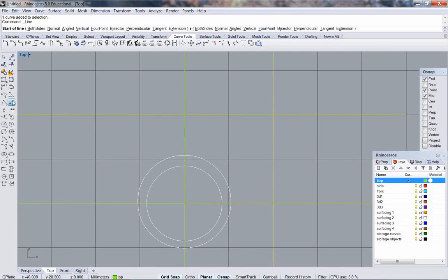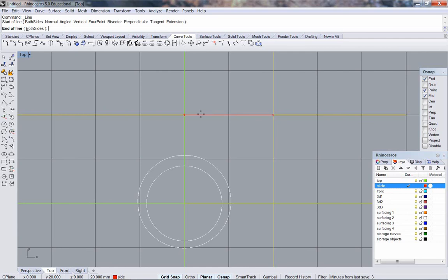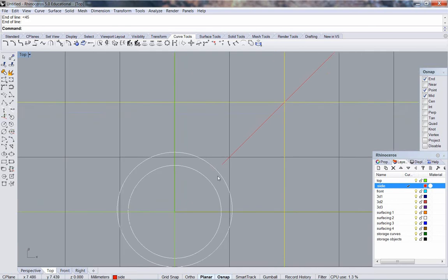And while I'm at it, draw our miter line. Starting here, constraining 3 things in this case. I want both sides, well actually 2 once again. Really the only thing I need to constrain is direction. So backward facing arrow, that's shift comma key, 45. That locks it into a 45 degree angle. And I'll stop just outside of the